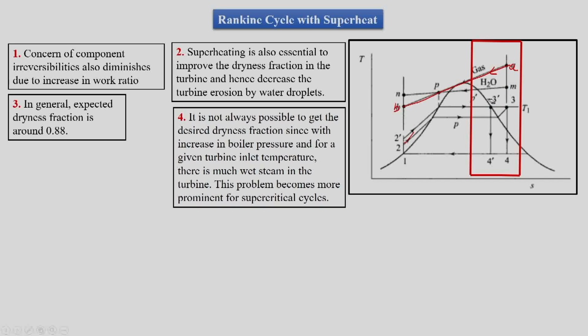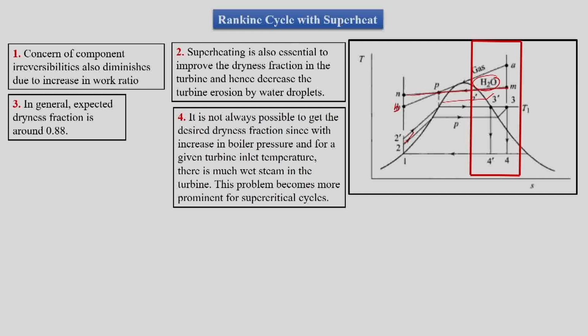It is possible. But now instead of gas, if we have high pressure water, heavy water, which is supplying the heat, as in the case of a nuclear power plant, then we cannot have higher and higher superheat possible with water as the medium which is the source of heat. So in such a case, if we want to go at higher pressure, then less and less superheat is possible, and at a certain pressure we would not have superheat possible with the high pressure water which is giving the heat. But in case of gases, yes, it is possible.